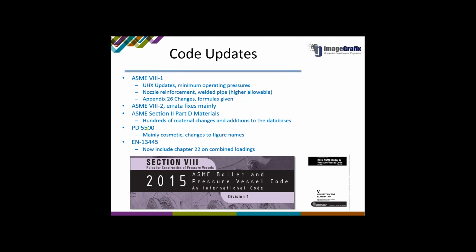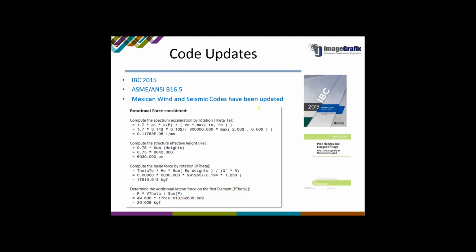Then coming to PD 5500, there were some cosmetic changes, no more calculation changes, they only fixed some issues. Okay, same in the EN 13445, they now included chapter 22, which is on the combined loadings.